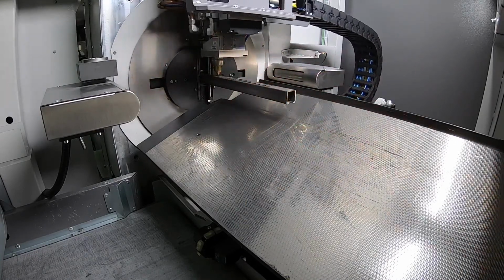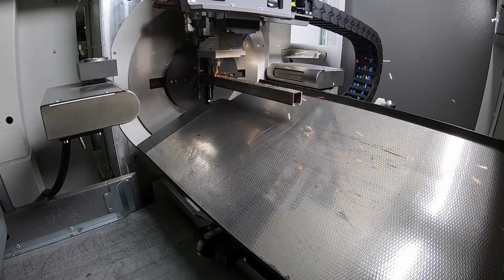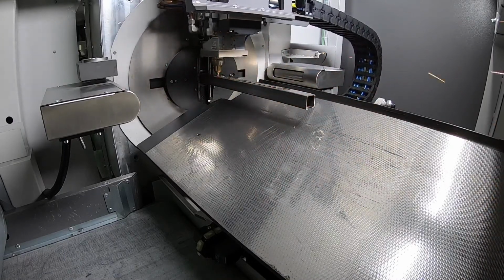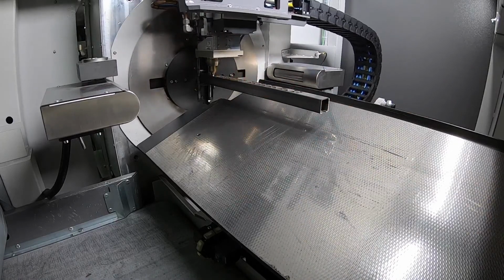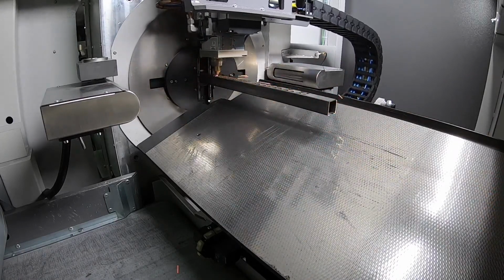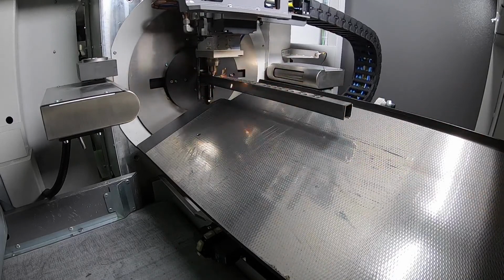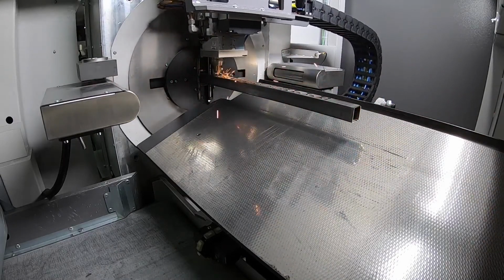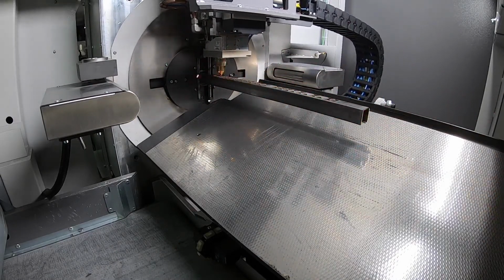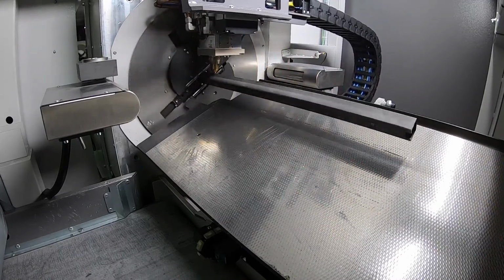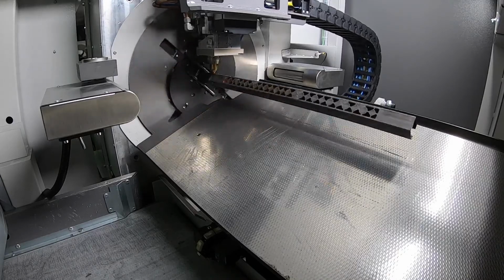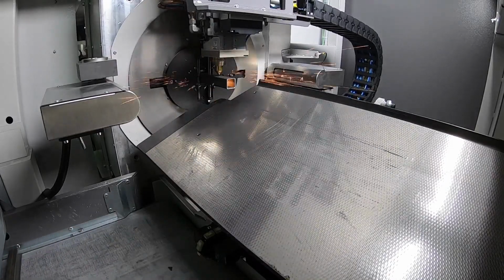So the quality quick cut is a feature that allows us to have much better quality, much better cutting stability, and it consists in X movement, so the head will move instead of the tube. It will guarantee no vibrations on the tube, and the head has a 30 millimeter path where it can move along the tube, just keeping the tube still and improving our cutting quality.